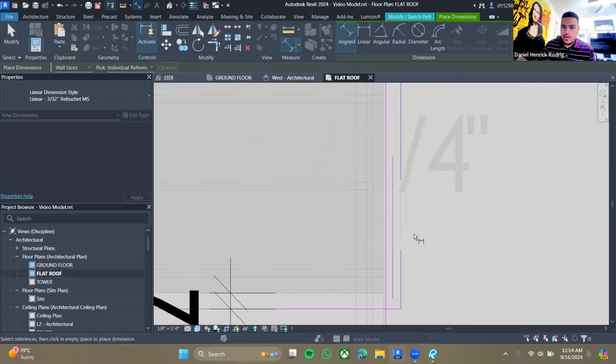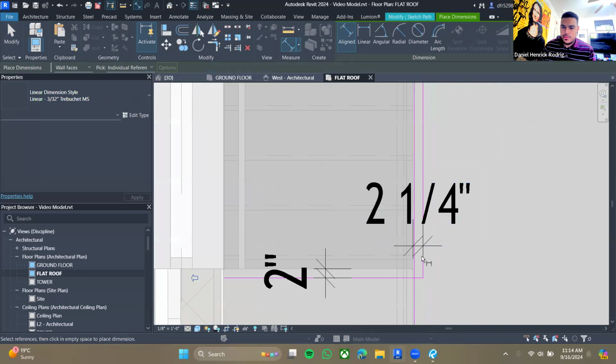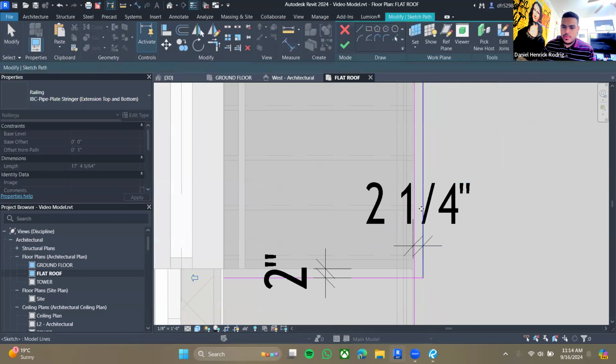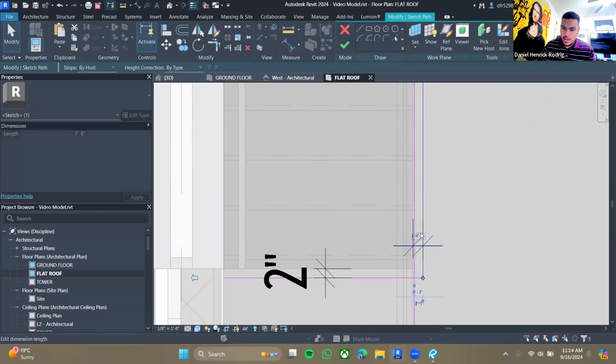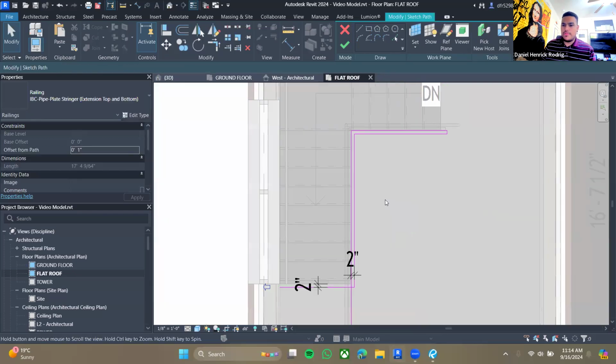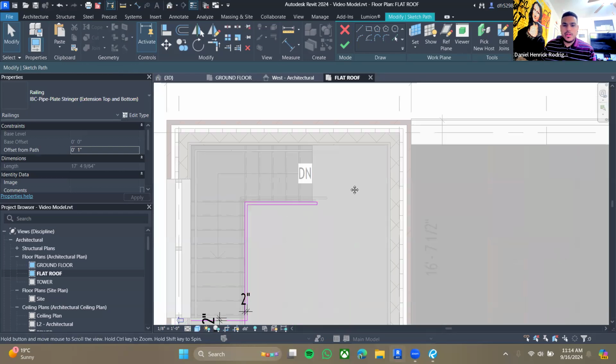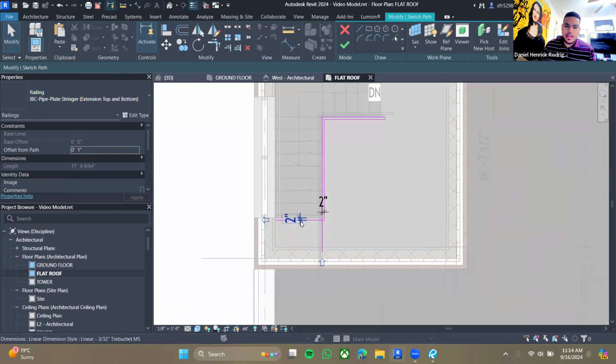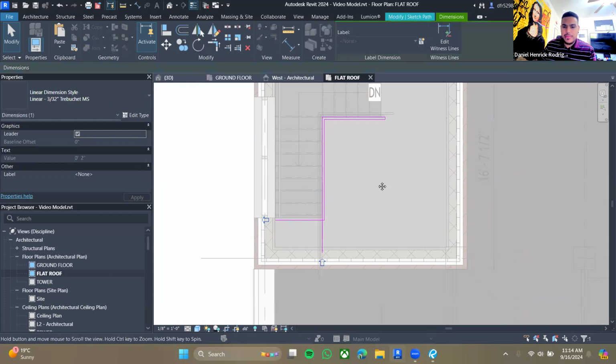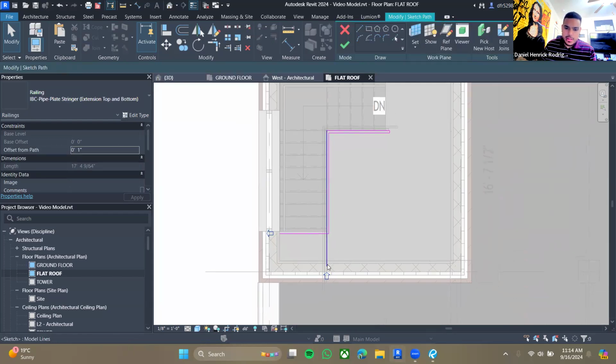And then from the corner, let's just change that to 2 inches. 0 space 2. There we go. Very consistent. I think I already made this 2 inches. And now let's just hit OK. And it does look a little bit confusing because the lines overlap. But if you notice, you can have the railing going up the stairs, takes a right, and then this one is just within this floor. Let's hit OK.